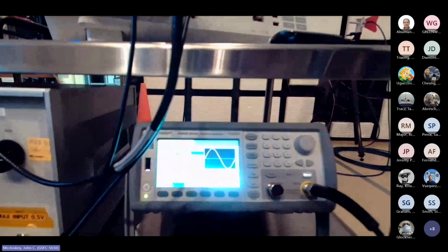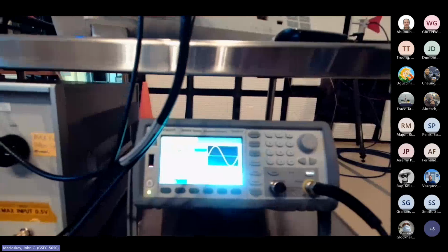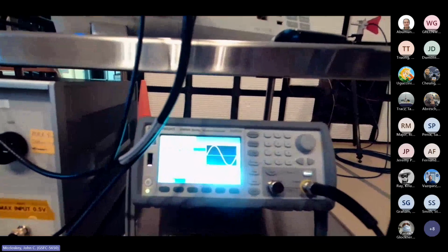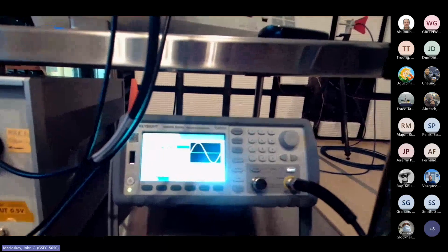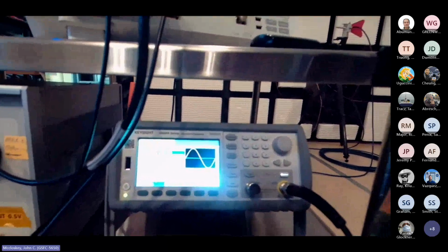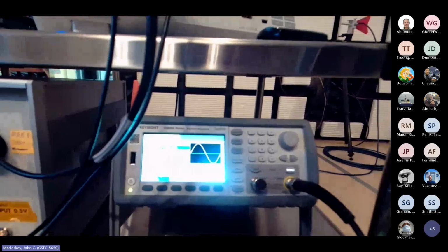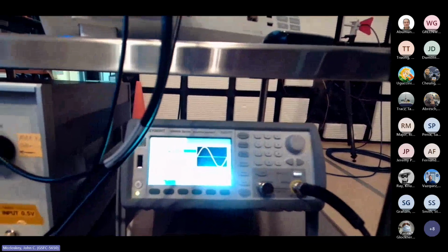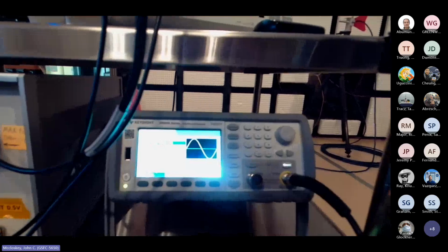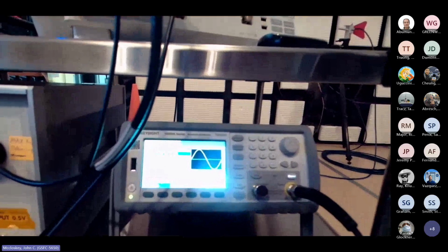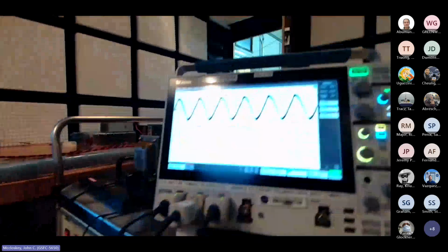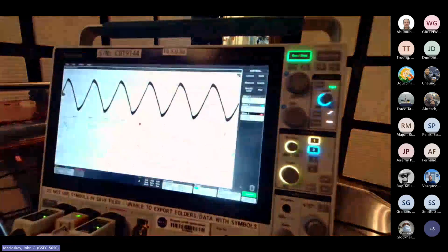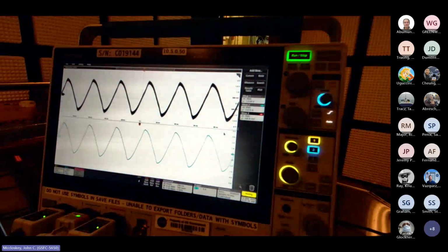If you're not able to establish the 1 volt RMS or whatever your limit is, but you get to this pre-calibrated level first, you stop. And as I said on Monday, you still meet the requirement. There's no waiver necessary for saying we weren't able to get the voltage, we had to stop at the pre-calibrated level. No, you've met the requirement. You've met the full intent of the requirement. Because you don't want to keep trying to crank up to 1 volt RMS when you've got a low impedance and start putting a lot more current into your unit under test than you want. Okay, so with all that, let's get cranking.